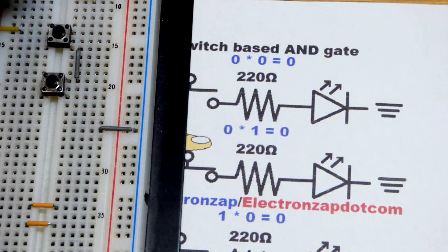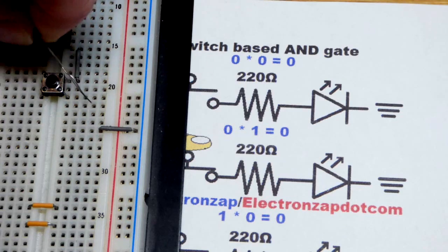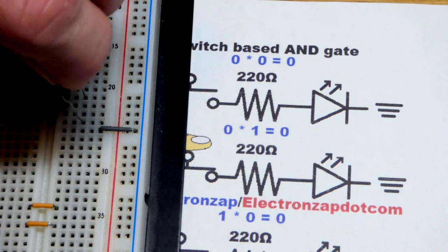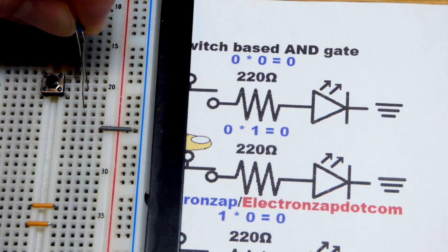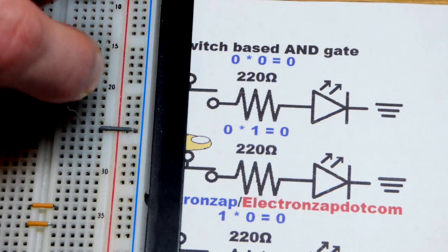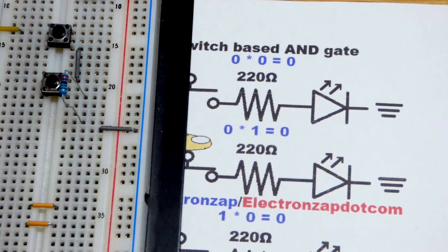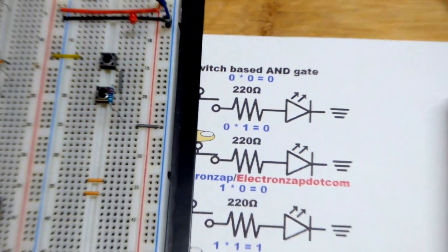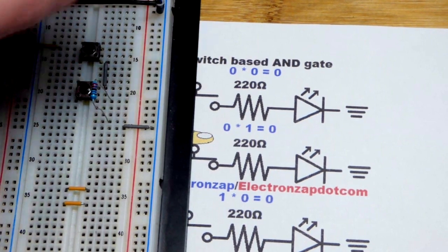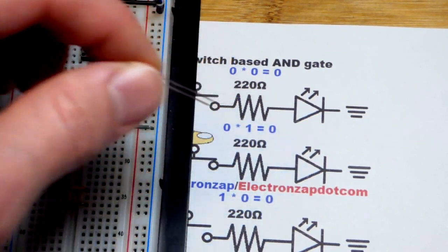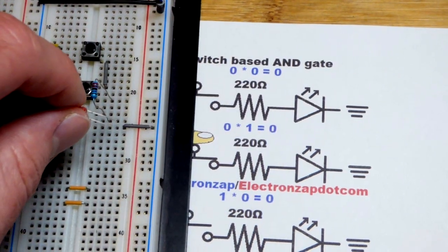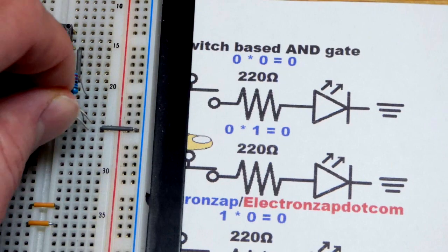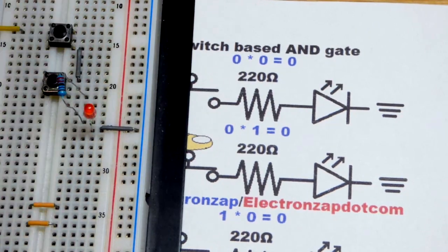So now we have our two switches in place. We'll take a 200 ohm resistor, go from the bottom of this switch to one row away from that jumper right there, and the leads are bent kind of at an angle. These are cheap resistors. Their leads are not as thick. They kind of bend easier, but I got a lot of values for not a whole lot of money, so it was kind of worth it. So in any case, long lead, the anode goes to the resistor there. Short lead, the cathode goes to ground. Just your basic LED protected by a resistor circuit.